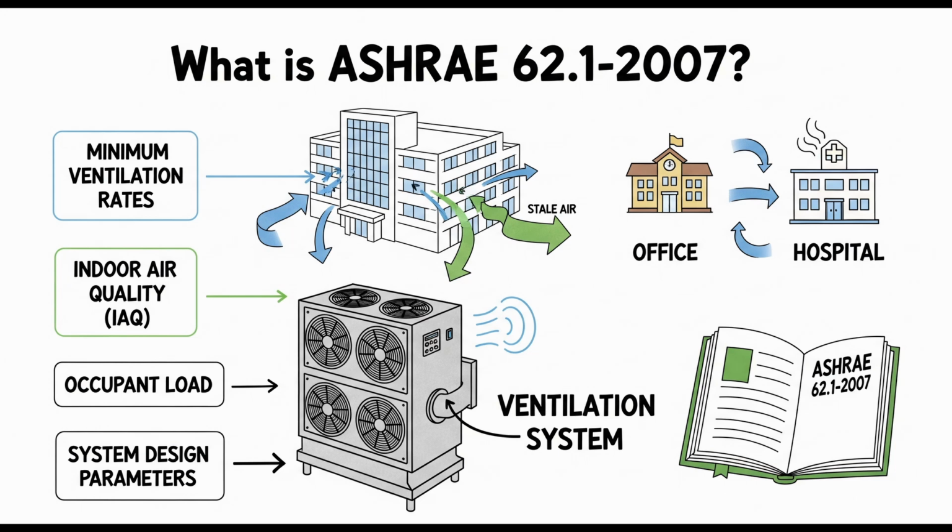Precisely. Section 5.17.3 lays out recirculation limits. The key insight here is just preventing cross-contamination. Makes sense. Class 1 air, you can recirculate it or transfer it pretty much anywhere. Class 2 air, you can recirculate it within its own space or transfer it to other Class 2 or Class 3 spaces, maybe restrooms. But, and this is crucial, Class 2 air cannot be recirculated or transferred back into Class 1 spaces. So no nail salon air going back into the general office area. Exactly. You want to keep that separate. And Class 3 air usually needs its own dedicated exhaust system and generally can't be recirculated into occupied areas at all. Makes intuitive sense. Keep the potentially yucky air away from the clean air zones.